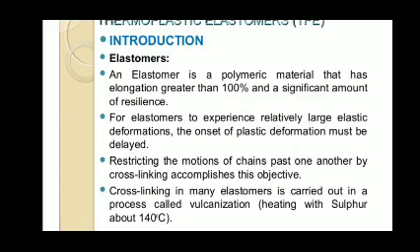An elastomer is a polymeric material that has elongation greater than 100% and a significant amount of resilience. For an elastomer to experience relatively large elastic deformation, the onset of plastic deformation must be delayed.